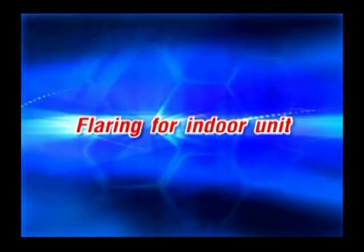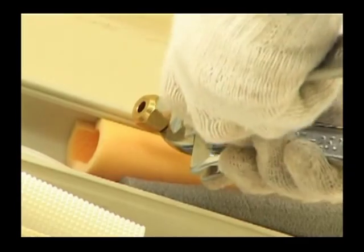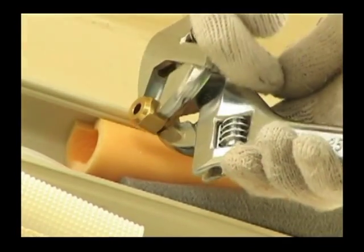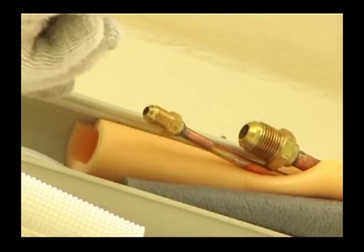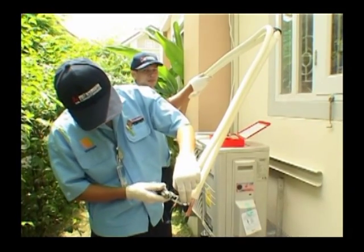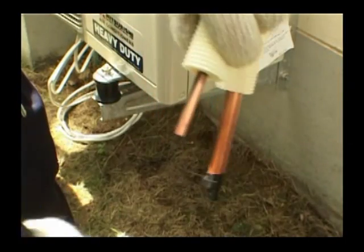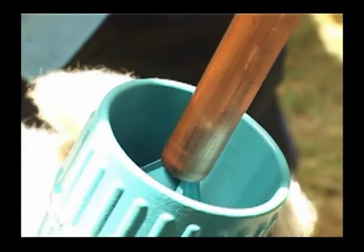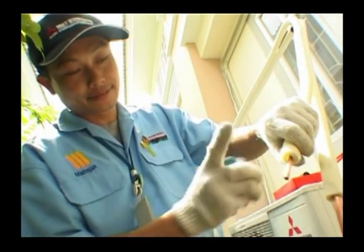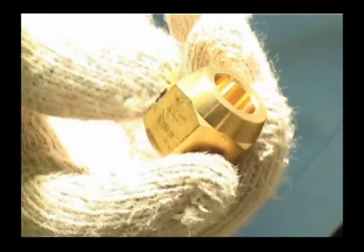The flare method for the indoor unit. It begins with using a wrench to remove a brass flare nut from its union. Cutting off the ends of both copper tubes and smoothing the tube ends with a reamer. Cut the tubes while holding their end downward to prevent remnants of copper from entering the air conditioning system.